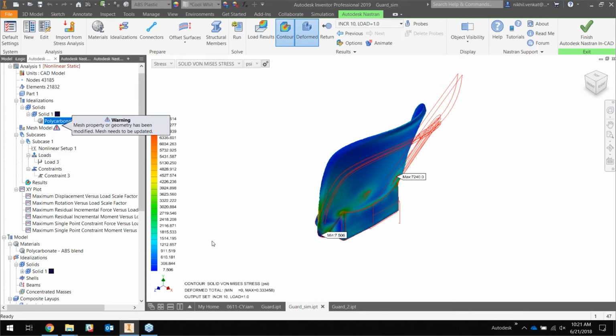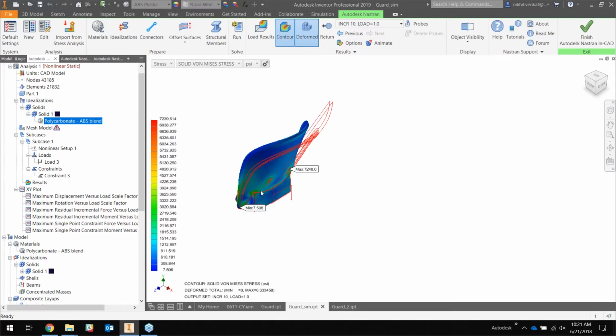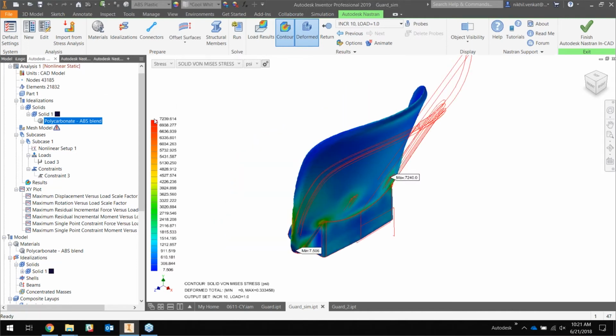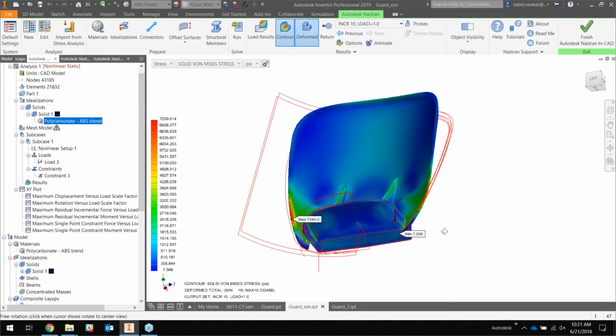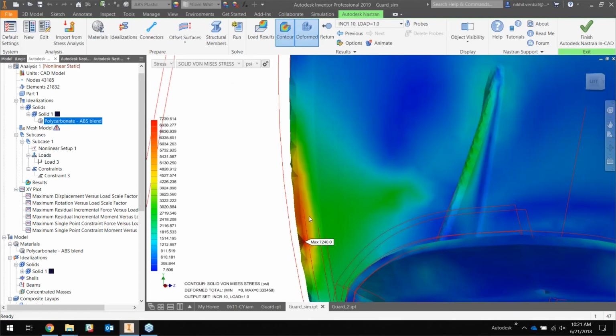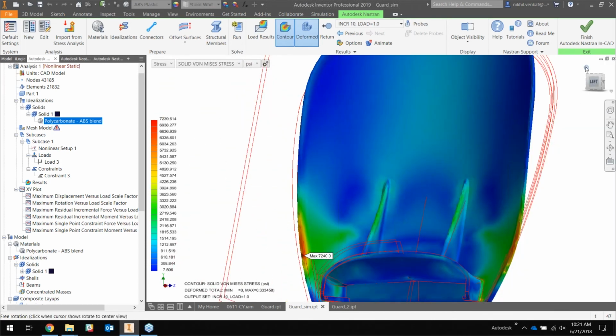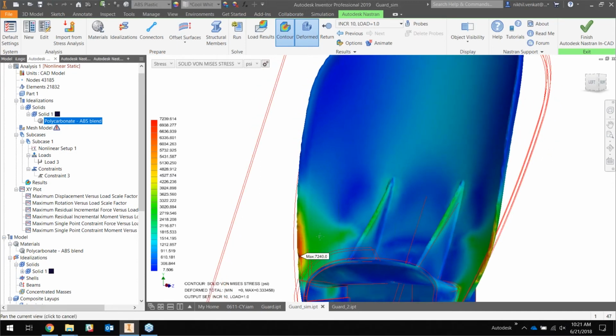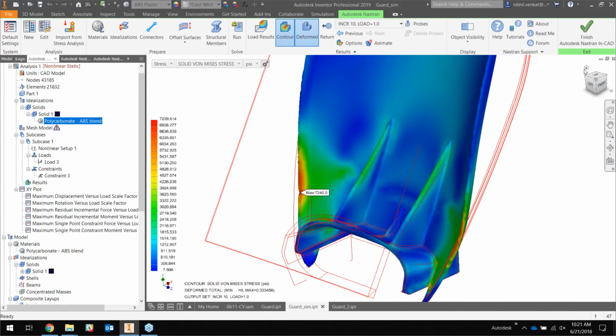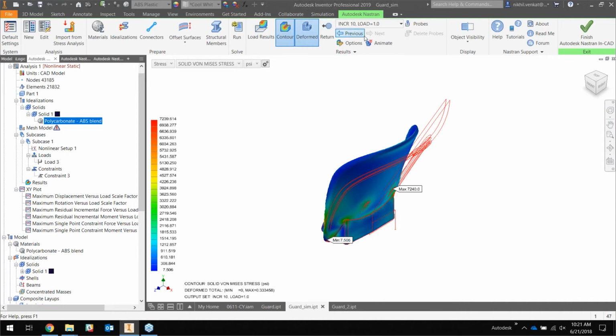First of all, just the basic stress value itself. And again, I haven't changed the mesh on this. I haven't changed anything else on this except that this has gone from a linear static to a nonlinear problem. The stress on this has actually increased, which is fine. But notice where the stress concentration is. Notice where the hotspots are. That now is at these edges, at the outside edge of this.